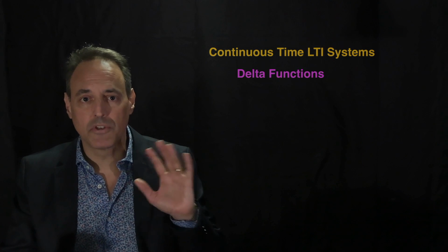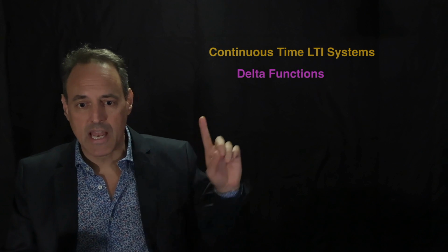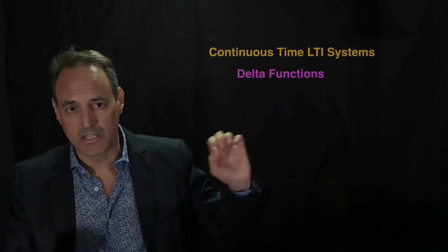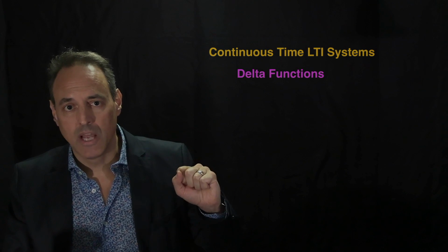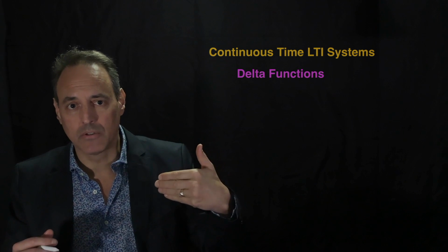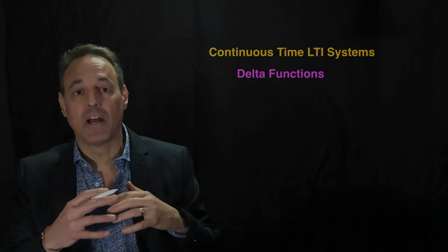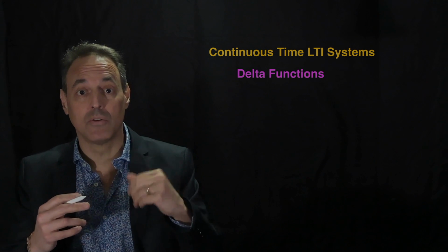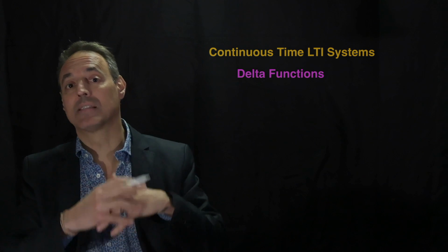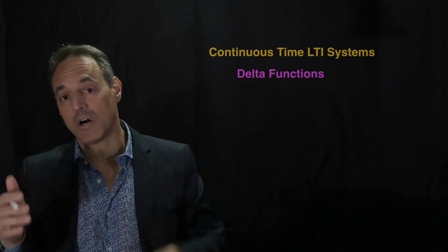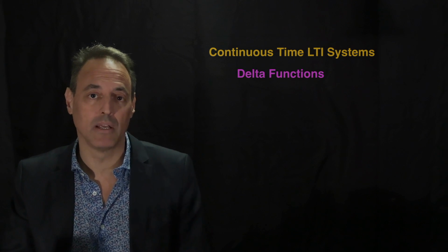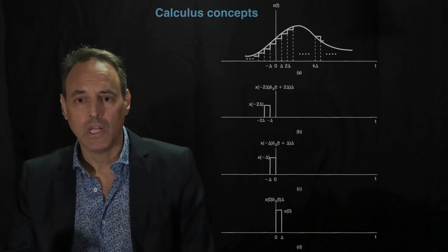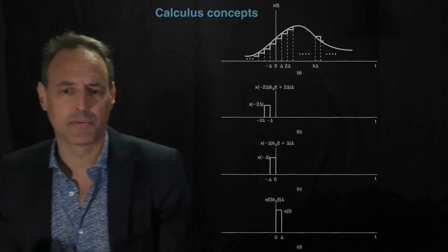We've already done this for the discrete case in the last lecture, and now we want to do this for the continuous case. I want to give a delta function kick, watch the response, and then if I have an input signal into my system, if I know how it behaves to a kick, I can basically sum up all the responses over all of time into an integral formulation based upon understanding how it behaves according to one delta function kick. So let's go back to our calculus concepts.